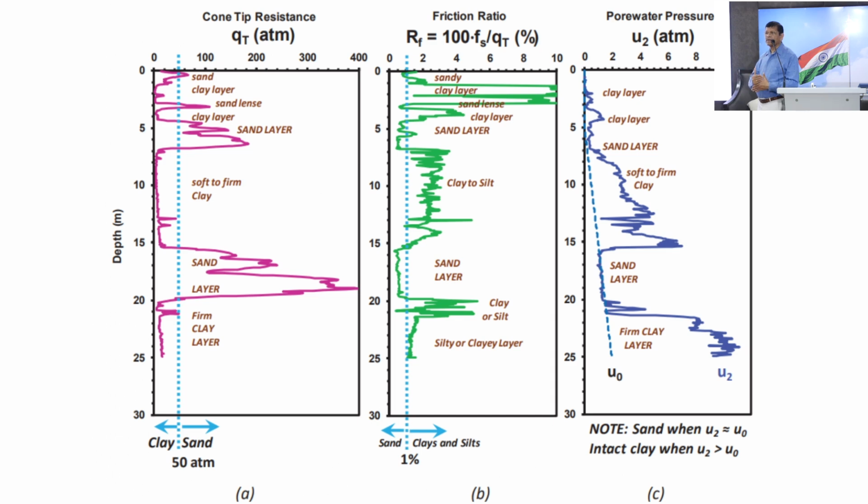But for a regular event, where it is a seismically active region, definitely the dynamic pore pressure is also helpful. But in most of the cases, we look into an area where it is not seismically active, but normal, and we call it static liquefaction. In those static liquefaction cases, our static pore pressure is important.